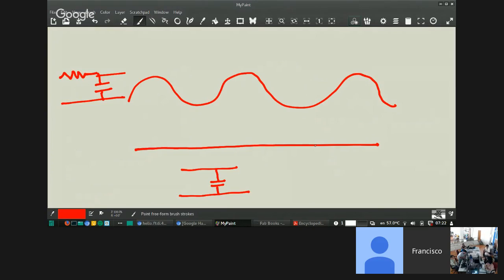But on a power line, if you put a resistor, it will waste a lot of power as heat. So we don't put a resistor over the power line. Maybe we'll put it as a pull down resistor for stability or something. But what you drew over there, we don't use on a power line. It's perfectly fine on a signal line, not for a power line.